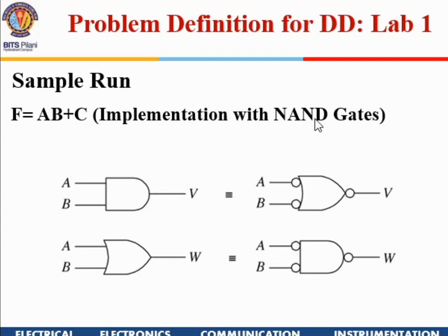It's a combination of an AND gate and an inverter inside the gate, when I'm speaking at the transistor level. Okay, so this is an AND gate. It is equivalent to an OR gate: if you invert the inputs and the output, an OR gate will become an AND gate. Similarly, if you invert the inputs and the output, an AND gate will behave like an OR gate.